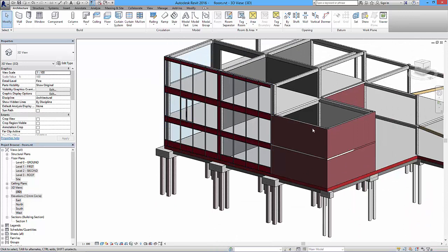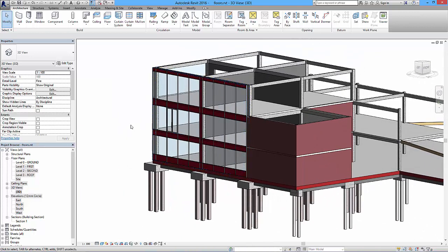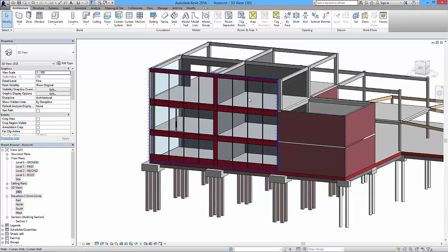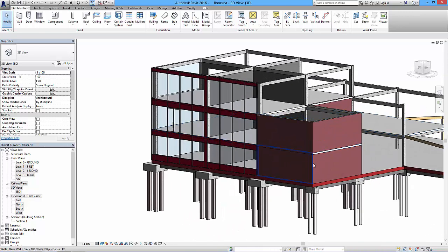Doors to other bits and pieces, they're just so easy. So again, it's too easy to show you as a supplementary to what we'll have looked at in class, but that's your wall bit covered. So concrete walls, modifying the profile of the wall we've looked at there. We've applied curtain wall systems, and we've applied a typical sort of basic wall. Things like stacked walls and applying sort of foundations to walls, etc. We'll discuss in class, but that's as much as you need to know for the purposes of this.